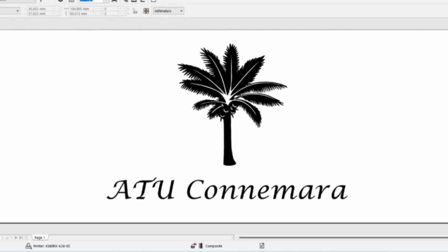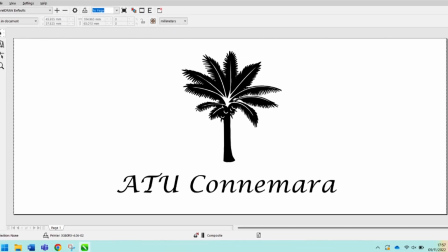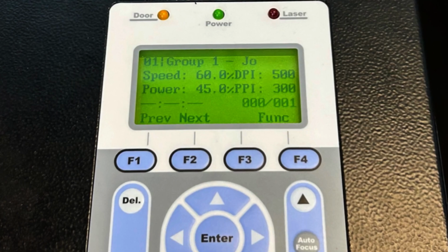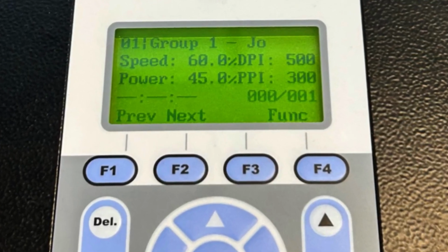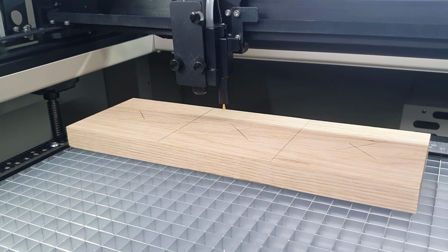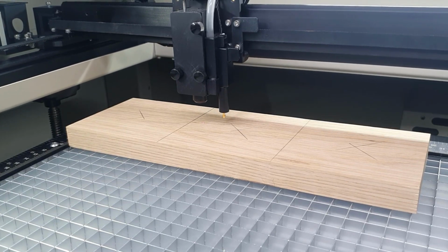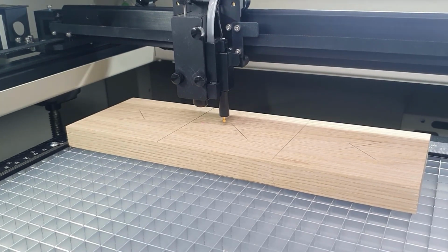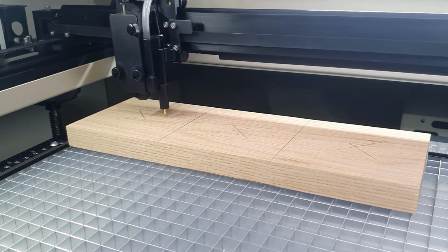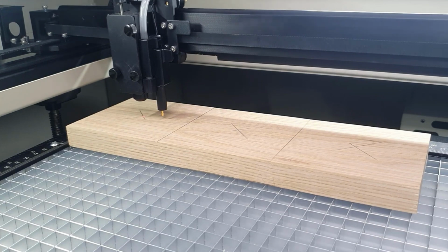Always use Print Preview before selecting Print to ensure everything is laid out correctly. Once you select Print, the job will now appear on the GCC X380's control panel. Before printing, the focus sensor must be calibrated to be approximately 6 mm above the surface of the piece. The laser must be positioned in the center of the piece, and you are now safe to begin engraving.